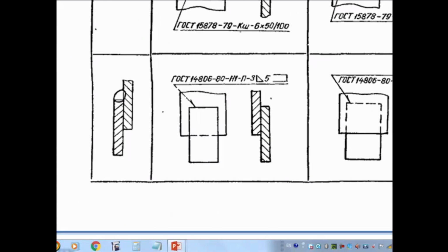Here we can see different types of representation. The triangle is a fillet weld, and this is the size of it, and another value. One leg is this one, and the other leg has a different size. And also this kind of symbol means not a closed shape, but all around except one side. So this side and that side should be welded, and the other side is open.